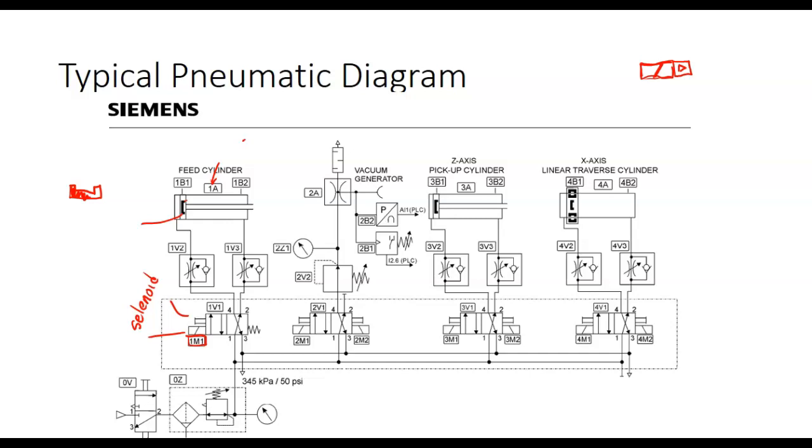And then it's got an analog pressure sensor, which would actually give us a voltage readout that we can convert with either an indicator or with our PLC through a program if it's got an analog input. And it's hooked up, by the way. It's just not in the current programs. So this line is set up so you could rewrite the programs and bring all this analog stuff into play, but we haven't fooled around with it. Scared to, in fact.